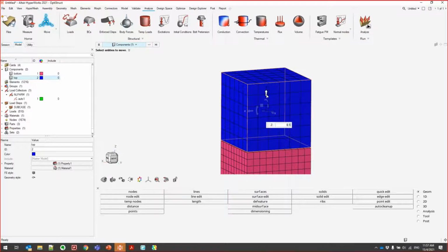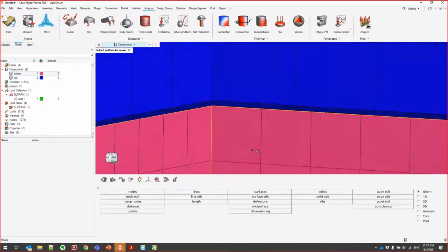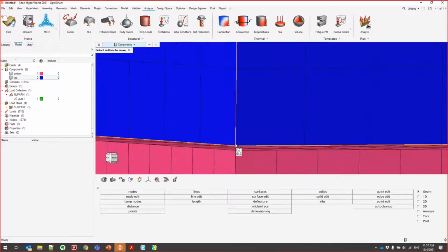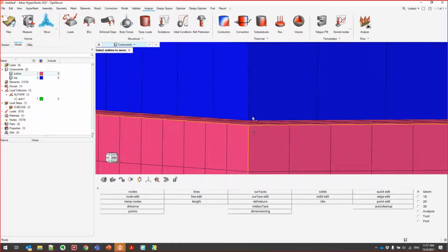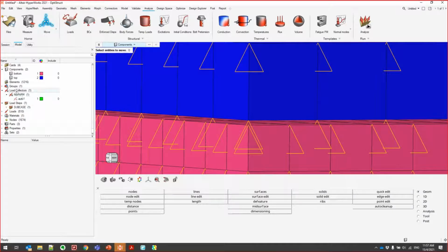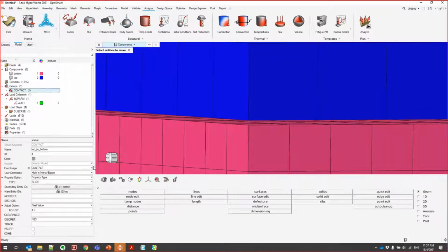Let's say initially the geometry has this gap, but I want it to be touching already, so I set my clearance equal to 0. To do that, you go to contacts and find this clearance here. Clearance equal to 0 means you will already have contact at the beginning. If I put 0.05, it will move halfway downwards before it generates that contact.